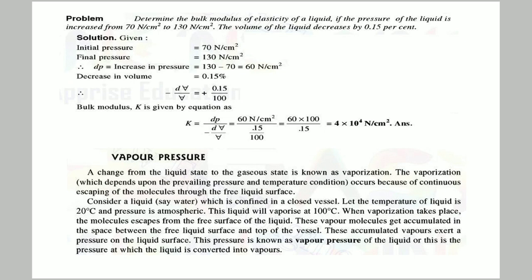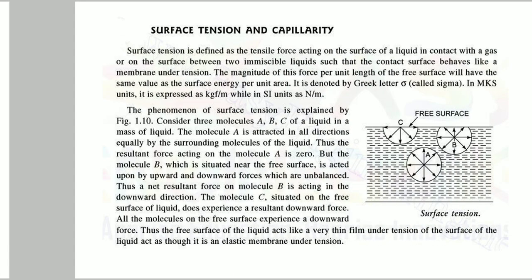So, if the pressure is brought below the vapor pressure, or the pressure is equal to or less than the vapor pressure, boiling starts, however low the temperature may be. If the water is at 20 degrees Celsius and the pressure is decreased below the vapor pressure, the liquid automatically starts boiling. So, vapor pressure is highly significant. We should know the vapor pressure of various liquids.